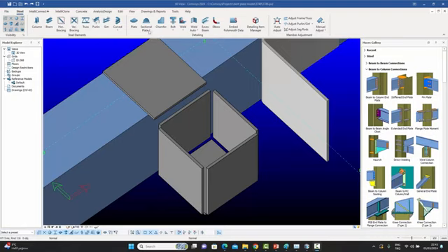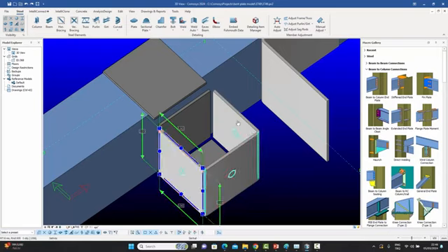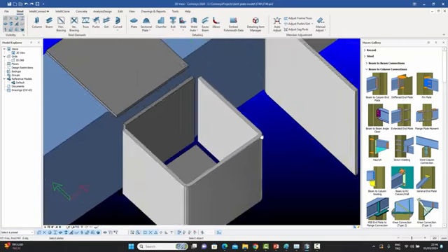What you do is you go here. Like I said, you use the cylindrical bent plate command, and you click on it. And then it allows you to choose either two plates or one existing bent plate and another plate. So I'm going to choose this plate and this plate. And immediately it joins them together. And now this is no longer a normal plate, but this is a bent plate. I can continue by selecting this bent plate and this plate, and it joins those two together as well. You can see from there, it's joined them together.